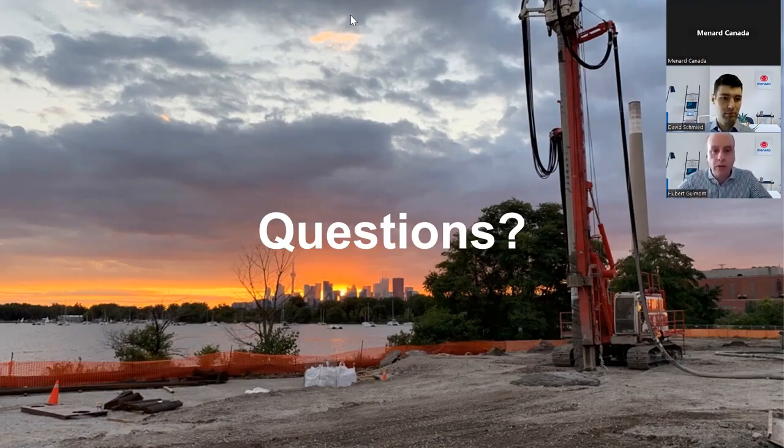I'll go through a few questions now. We still have a few minutes left, so I can look at the chat here. We have a question about the risk of liquefaction when using any of these techniques, let's say dynamic compaction, or vibro compaction, or even stone columns. When we're doing the ground improvement, we need to make sure that we're monitoring the site in order not to create a problem.